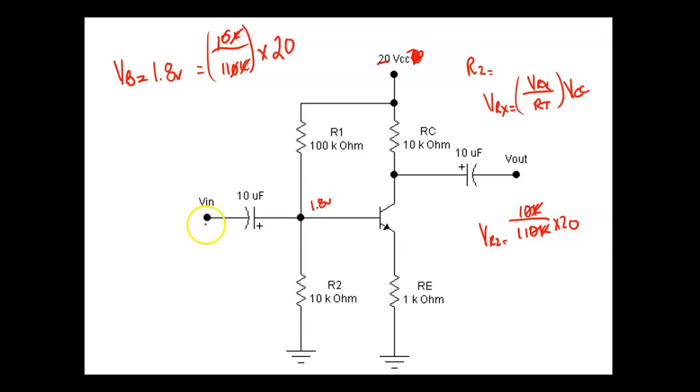Well, the problem is over here, this is an AC source. So from a DC point of view, this is seen as common. We just proved that. So that means this is plus 1.8, this is 0 volts DC. Which side is positive? What's more positive, 1.8 or 0? Okay, so that means I have to put the plus toward there. Now over here, this is 0, it's going to be AC out, right? You understand? So a DC source sees an AC signal as 0.